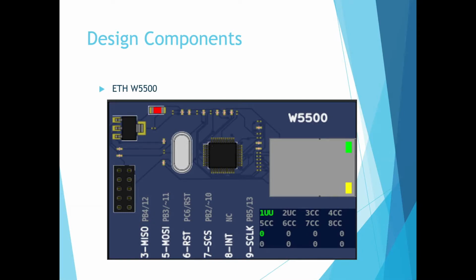Firstly, we will see about the W5500 Ethernet shield. The W5500 Ethernet shield can provide our projects with internet connectivity. W5500 enables users to have internet connectivity in their applications by using a single chip in which the TCP/IP stack, 10/100 Ethernet MAC and PHY are embedded. The shield also has two Grove connectors and a micro SD card socket to support projects which require storing large amounts of data from Grove sensors.